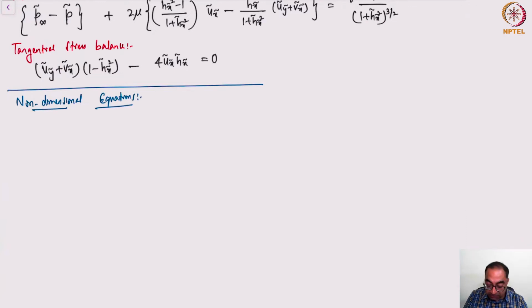Now, I'll give you an idea. Terms like del u tilde by del x tilde simply become u naught by L times del u by del x. Similarly, del v by del y simply becomes epsilon u naught by h naught del v by del y.